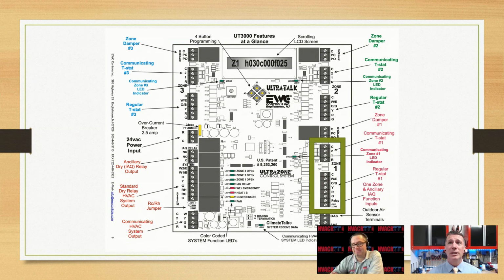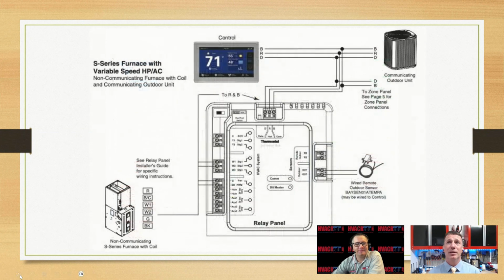All they're doing is taking analog inputs from a thermostat and creating the outputs and communicating to run our communicating system. Now, here's what I find intriguing about it. There are actually other products that have been out there on the market, some around long enough that they've even been discontinued. If we look at this particular one, this manufacturer had a board that allowed a communicating outdoor unit and a communicating thermostat to talk to a non-communicating furnace.